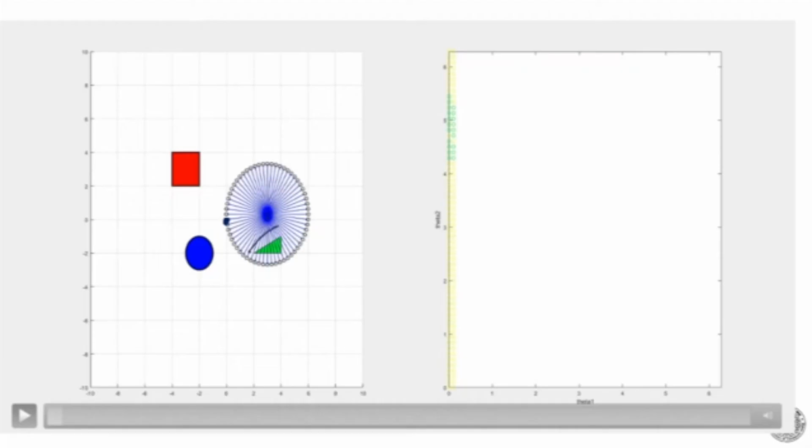Now wherever it is hitting there, right? So for theta equal to, I think it is a little bit more, it's over 5 degrees. It starts from 0, 1, 2, 3, 4 like that. Okay, so it is hitting here, so we color it by green. Okay, so this is how the program works, and this is how we are going from Cartesian space. So this is my Cartesian space, and this is my C space.